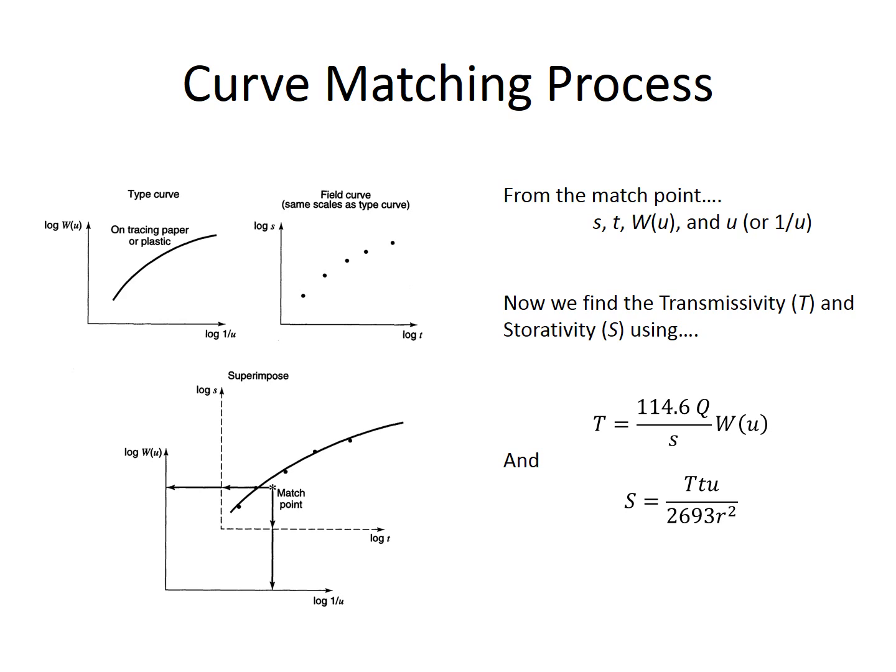I wanted to be sure to note that you have to be careful with units. In the example that I'm going to discuss shortly, your book wasn't careful, and I think they made mistakes, just being sloppy. Make sure you use a consistent set of units. If you're going to have Q in gallons, that's going to make it confusing. So you'll probably want to convert to cubic feet per minute or cubic feet per second in your Q, and make sure that your units match whatever you're using for drawdown and time. You'll see this in the example that follows.